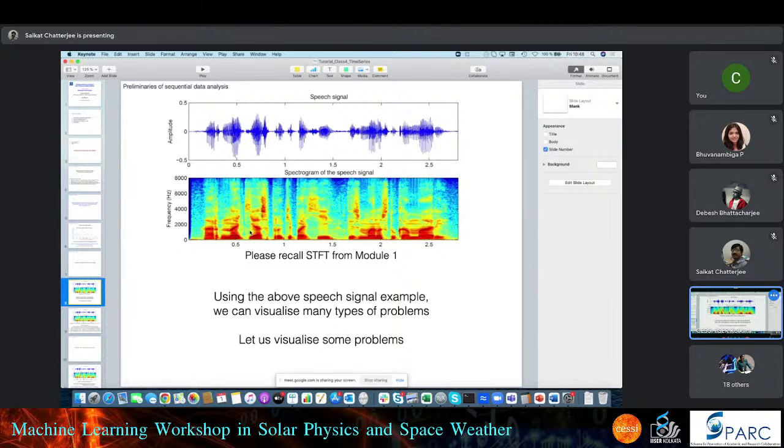But you can easily see from this picture that it gives you some explanation or interpretability of the time domain raw signal you are seeing here. From the raw signal, you really cannot understand much, except that there are some parts of activity. But in the frequency domain you can figure it out. For example, this portion here is much more periodic, and then this is very noisy, and then again it is more periodic if you zoom in.